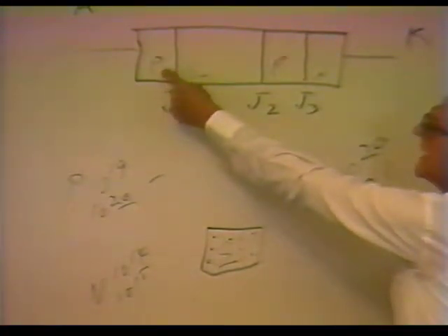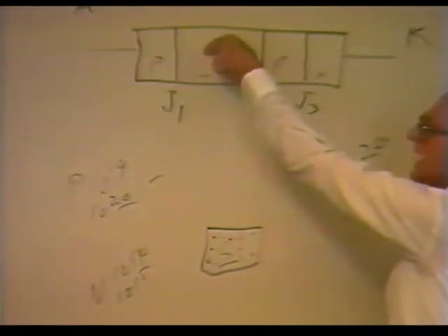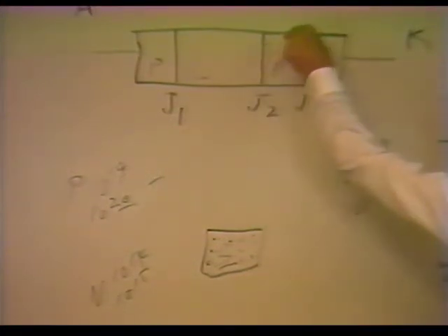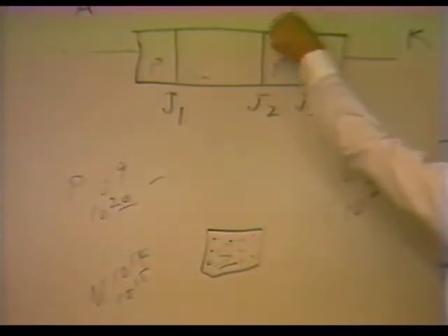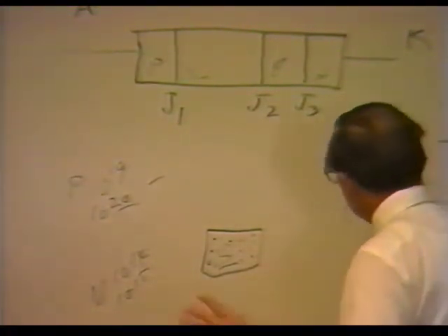The anode, P anode, is fairly heavily doped. Something we call the anode base, the N area here, is very lightly doped. The gate is fairly heavily doped, about the same as the anode. The cathode is quite heavily doped, more than anything else, because we're going to use the cathode as the emitter, and it's going to emit the carriers.